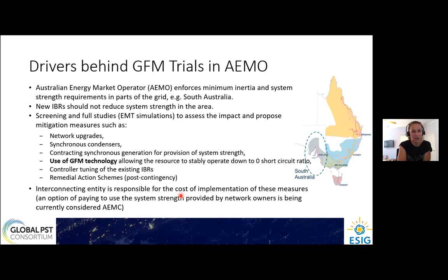So this got a lot of pushback in Australia because basically with every inverter-based resource in the area, if they are detrimental to system strength, they were considering putting a synchronous condenser next to the plant. And so it was all very suboptimal because they would each build a synchronous condenser to balance their own plant, and then somebody else would build another one close by, and there was no optimization as to where the synchronous condensers are planned.